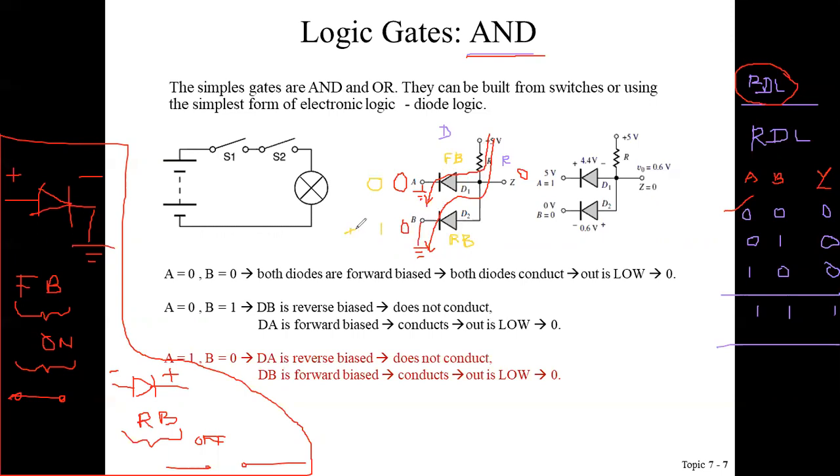If the plus VCC applied here is greater than this, this device is under reverse bias, so open circuited. Now all the source voltage is directly going to ground. So the second condition is also verified.